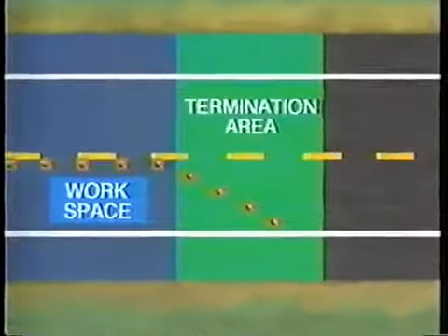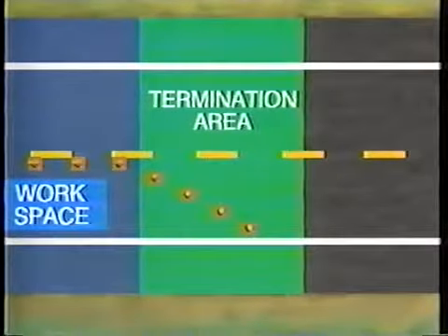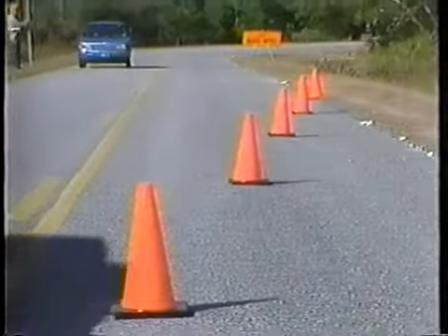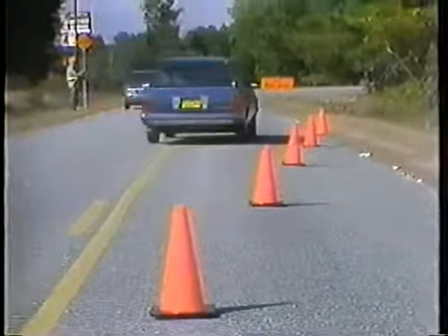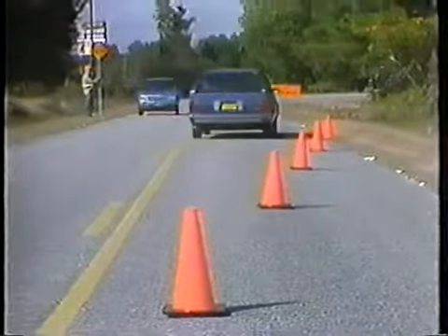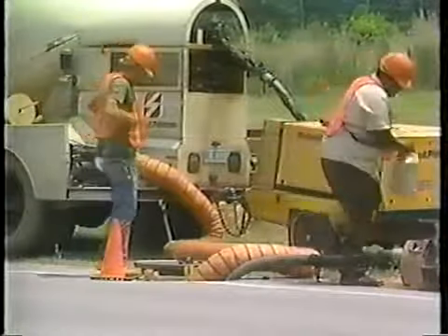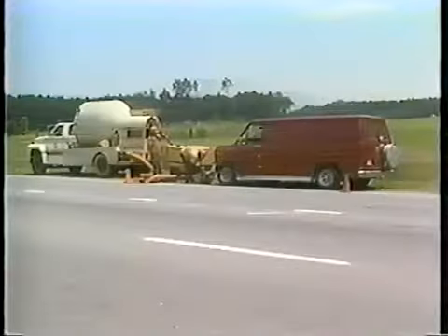The termination area provides a short distance for traffic to clear the activity area and return to the normal traffic lanes. It extends from the downstream end of the activity area to the end roadwork sign. A downstream taper may be placed in the termination area. For some work operations, such as a single location utility or maintenance repair, it may not be necessary to display an end roadwork sign because it will be obvious to drivers that they have passed the activity area.